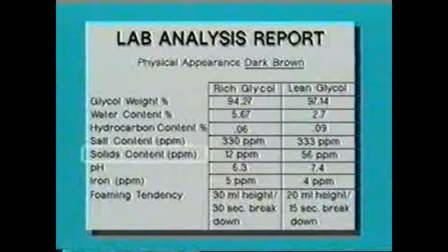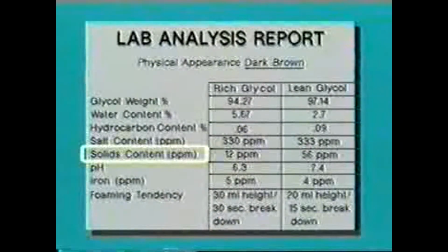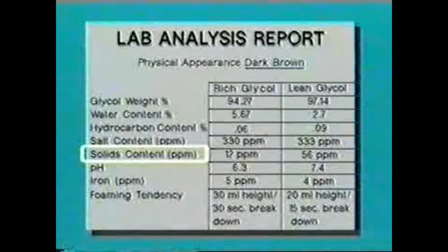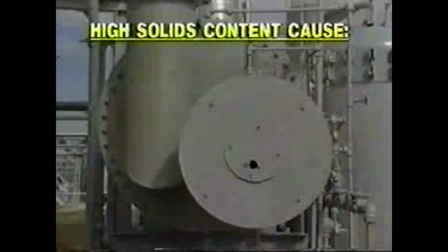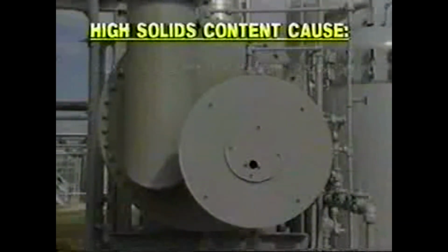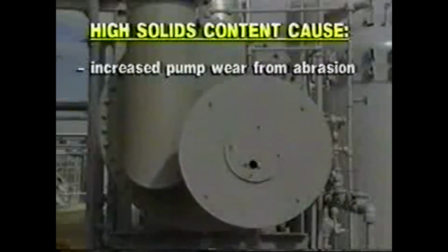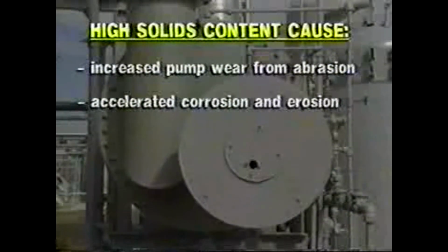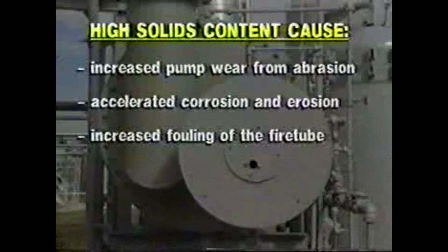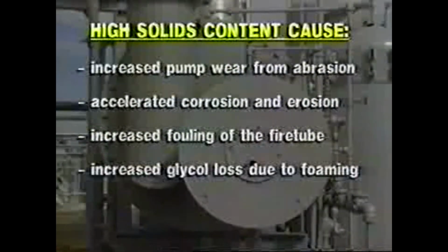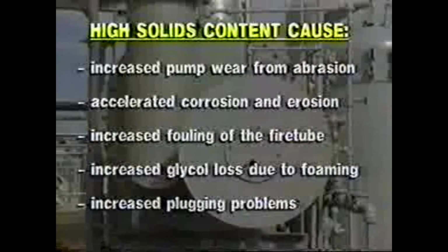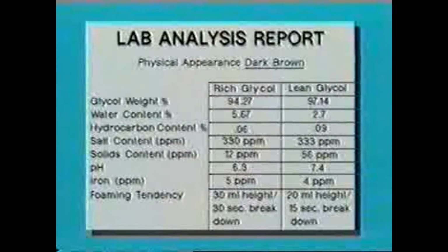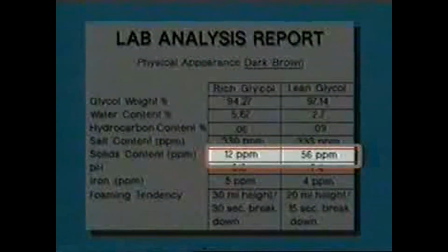Solids content refers to the amount of suspended solids in the glycol. Suspended solids should be kept below 0.01% by weight using filtration. High solids content in glycol causes the following problems: increased pump wear from abrasion, accelerated corrosion and erosion, increased fouling of the fire tube, increased glycol loss due to foaming, and increased plugging problems. The solids content of our sample seems to be in the acceptable range.